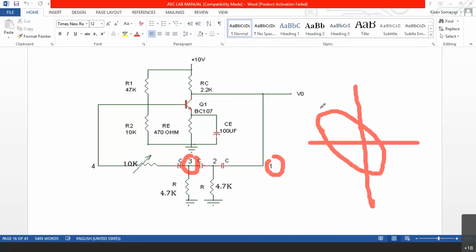Now here also procedure is same. Measure y1 and measure y2. Lower one is y1, upper one is y2. Measure y1 and y2. And the procedure is same. Only thing is, when you find this answer, you will have to make it as 180 minus, because now the Lissajous pattern is in the second quadrant.